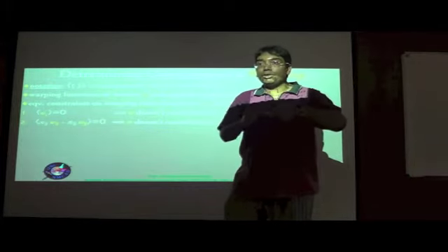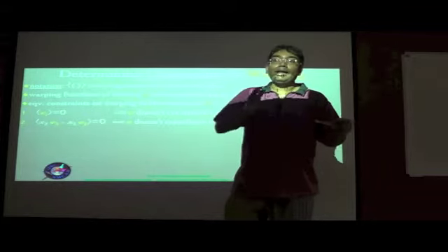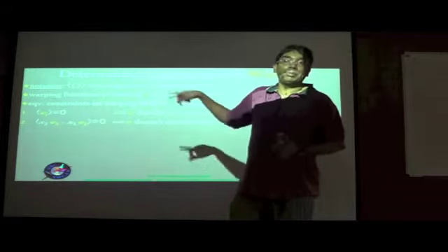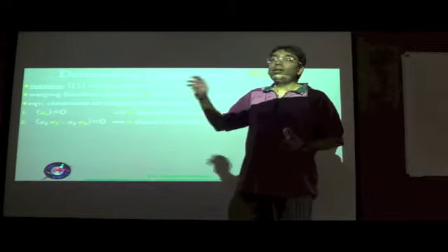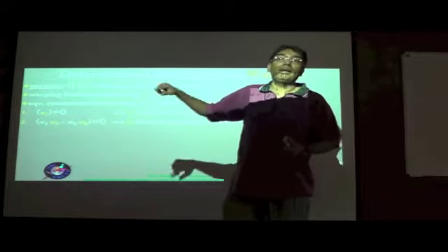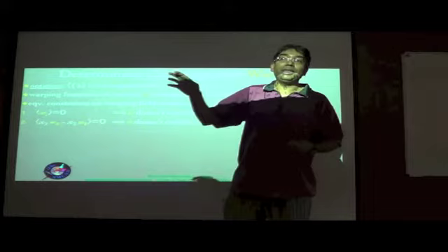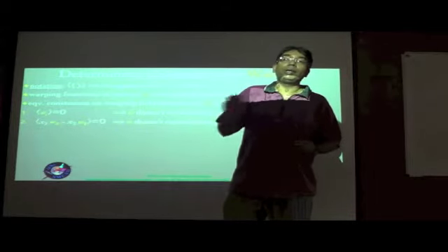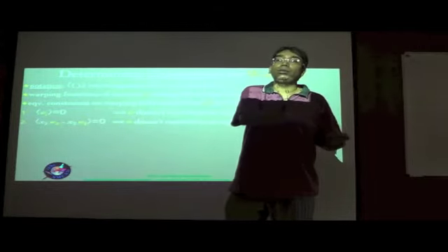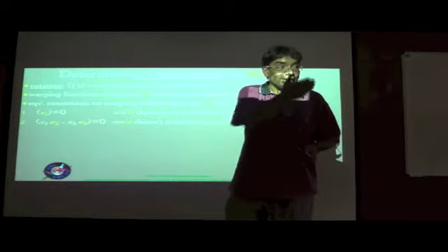The effect because of which kappa 1 prime contributes to the energy, that basically comes due to the W prime term. But the primary contribution from the warping is from that gamma A W. So if that contributes as 0, it's pretty much saying that W doesn't contribute anything to the energy in the general situation. Restrained warping. Exactly, restrained warping, yeah.